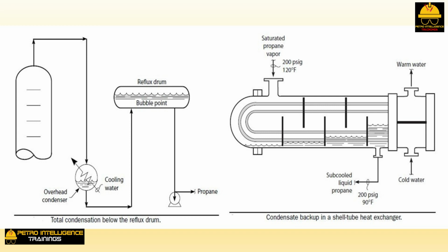The reason is condensate backup. The condensate backup causes subcooling, that is, the liquid is cooled below its bubble point or saturated liquid temperature. Perhaps a rat has lodged in the condensate outlet pipe. The rat restricts condensate drainage from the shell side. To force its way past the dead rat, the propane backs up in the condenser.